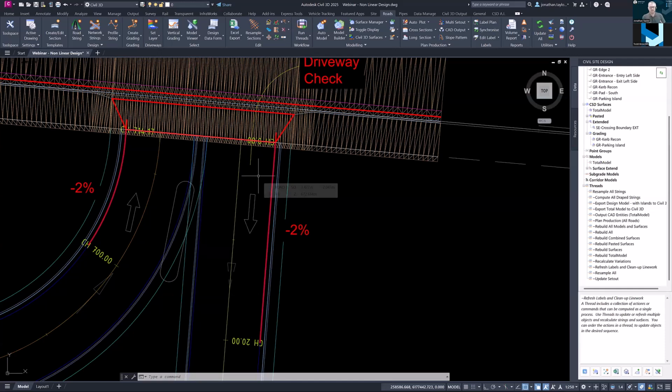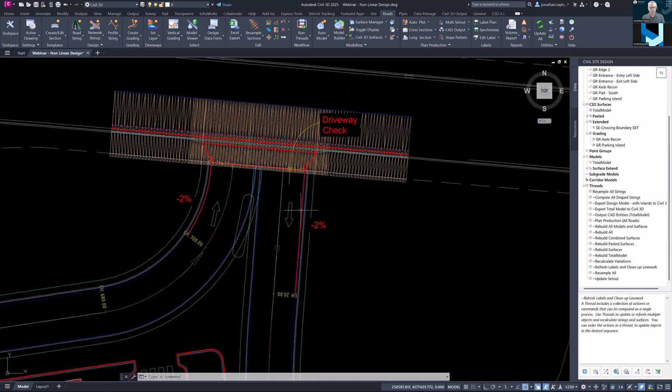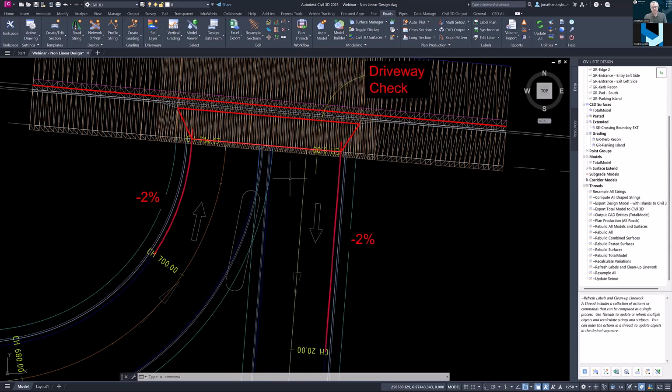Gone. The thing about this job is that I needed to snap onto things, and obviously the civil site design fast draw line work is not easy to snap onto at certain points for the geometry. So a lot of the time I was just quickly CAD output, draw, then running a refresh to clean up. All right, so we know the center line's in the right spot.